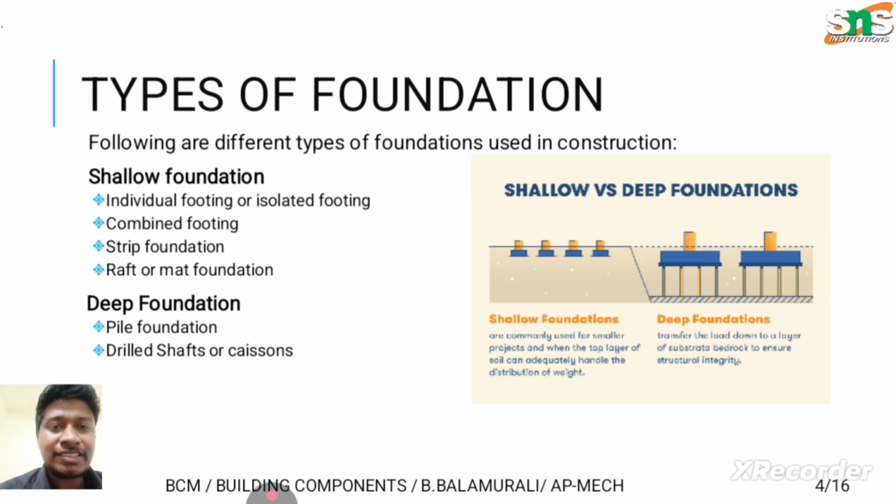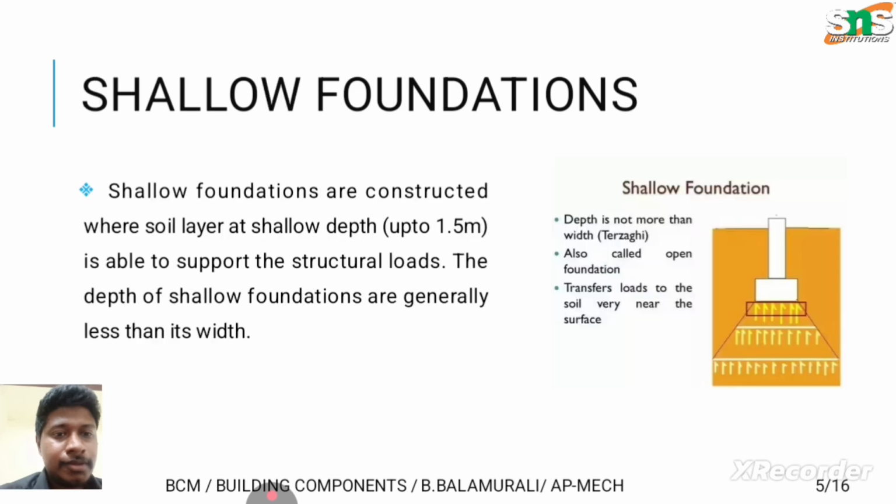They have various categories. Shallow foundations include individual or isolated footing, combined footing, strip footing, and raft or mat foundations. Deep foundations include pile foundations, drilled shafts, or caissons. Shallow foundation, as I already said, is up to 1.5 meters, not exceeding 3 meters, where the soil layer at shallow depth is able to support the structural load. The depth of shallow foundations is generally less than their width.